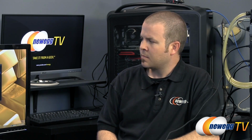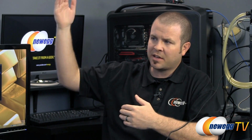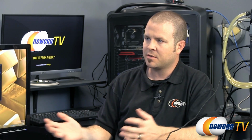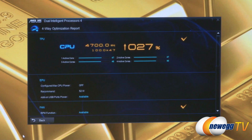We'll touch on more of the fan control functionality once we get into AiSuite III. What I've always liked about Fan Expert 2 is you can have a hodgepodge of fans in your system. They can be 3-pin, they can be 4-pin. It doesn't matter what vendor they come from. It goes in, it tests, sees maximum RPM, minimum RPM, and then you can adjust from there to get a suitable level of airflow as well as noise generation. Yep, 100% right. And the last portion is just a quick optimization of all the power management options.